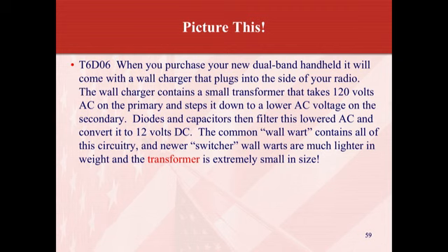So basically they're saying that your converter is taking your 120 volts AC on the wall. They call it a wall wart because I guess it looks like a wart when it's stuck on the wall, kind of a slang term. So it takes your AC down to 12 volts DC. In the old days they would step it down with a transformer, rectify it with diodes, and filter it with capacitors. But now they build everything into what they call switch mode power supplies. When you hear the word wall wart, it's a small, tiny switch mode power supply converting AC to DC.